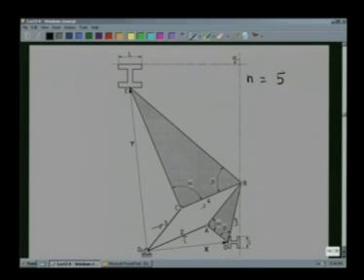Now let me count the number of hinges, J. We see there are 3 simple hinges at A, B and C. So J1 is 3. At O2, 3 links are connected, namely the fixed link 1 and link number 2 and 3. Since 3 links are connected at O2, this is a second order hinge, that is of the type J2. So J2 is 1.